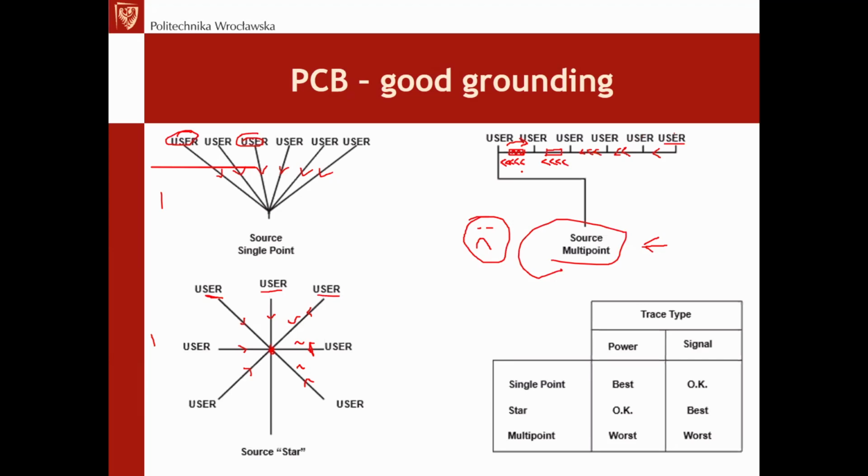This voltage drop may exist in the DC scale, for the power, but for high frequency signals it's especially painful, because it will cause drops at the high frequencies. What values can we expect within such a circuit in real life? I would say easily hundreds of millivolts. Not 100, but hundreds of millivolts. Such voltage drops may exist.